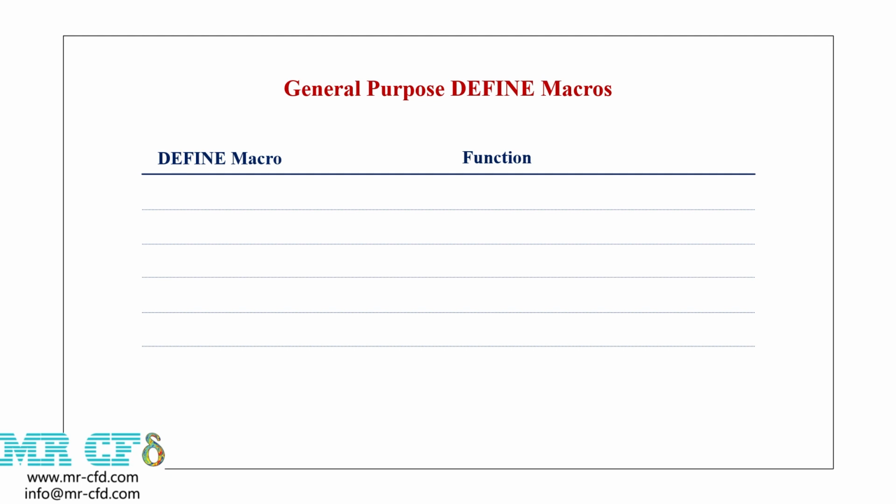Now we introduce each group of macros in turn. First, we introduce the general purpose defined macros. These macros relate to functions that are independent of the models used in ANSYS Fluent software. Here, we introduce some of the general purpose defined macros.